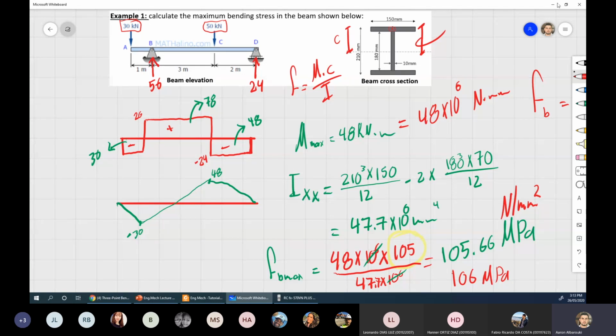So in terms of safety factors, think about it this way, guys. Please focus with me on this one here. When I'm talking about a strength of material to be safe, that means I have to make it stronger than what it is. Make sense? So instead of saying here I need 105 MPa, I should somehow use a safety factor to make this number larger.